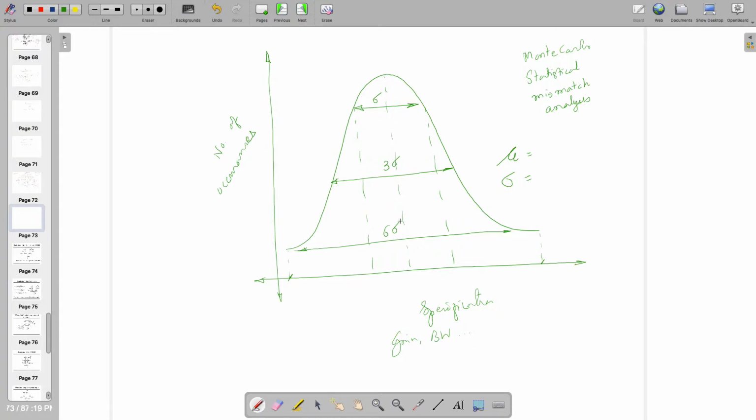or it's not failing on any of the runs. So generally this looks Gaussian because when you are doing this, there are two kinds of things: one is the transistor mismatch, sometimes they have process mismatch, and sometimes both.